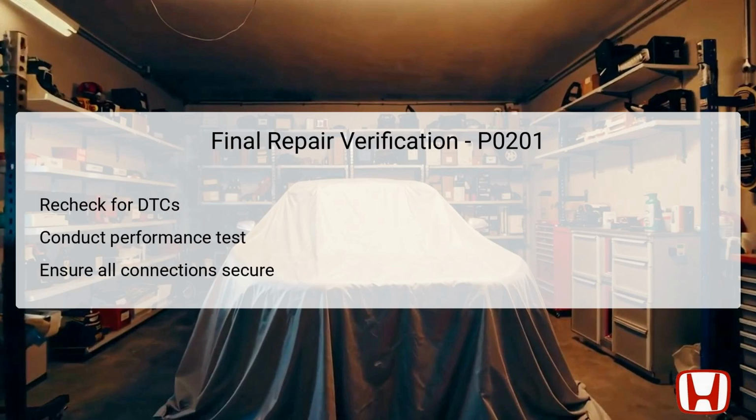After completing all the troubleshooting steps for DTC P0201, it's essential to conduct a final repair verification. Start by rechecking for any DTCs using the HDS to confirm that the P0201 has been resolved. It's crucial to see that no further issues are recorded, ensuring that the circuitry is functioning correctly.